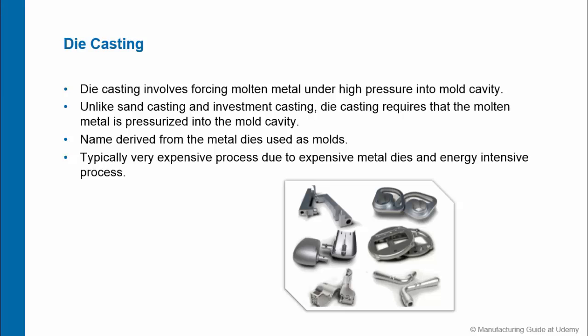In the other two processes that we learned earlier, sand casting and investment casting, we simply poured the molten metal into the mold and gravity did all the work. There was no force required. In die casting, gravity alone is not enough and we must rely on external pressure.